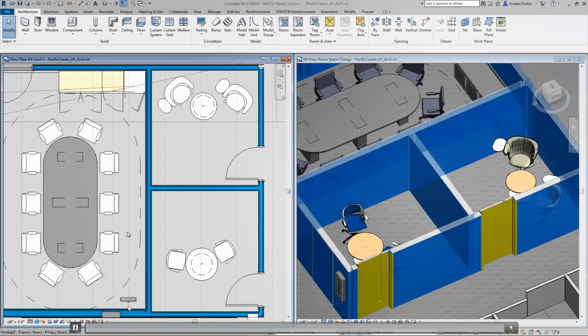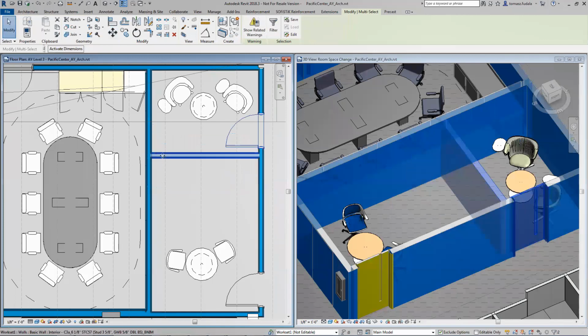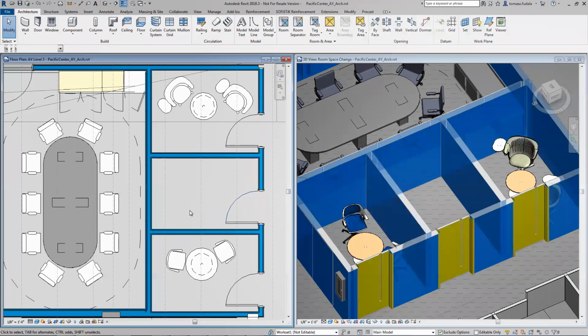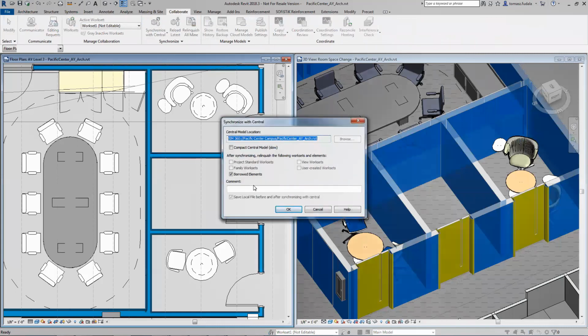So just to show where the two now work together, you want to request, as a structural engineer, an update from an architect to maybe move a wall or change the position of a wall within the architectural model that you have been working on. If you work with Collaboration for Revit, which integrates BIM 360 Design, you find that you can easily make a request to make a change within an architectural model based on the structural element that you have defined.